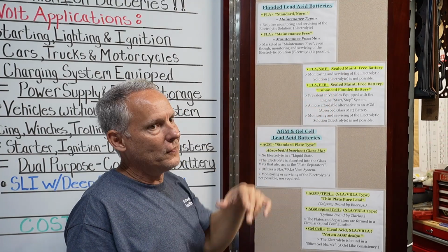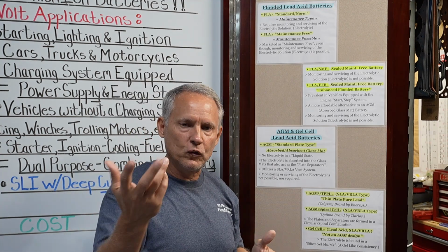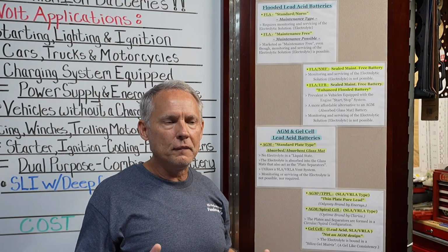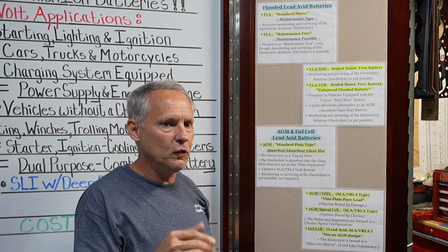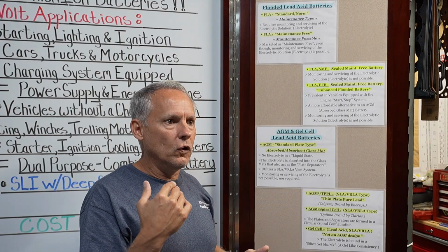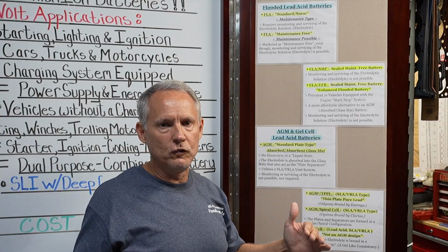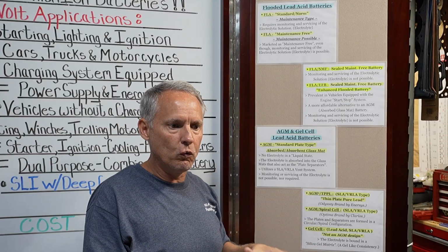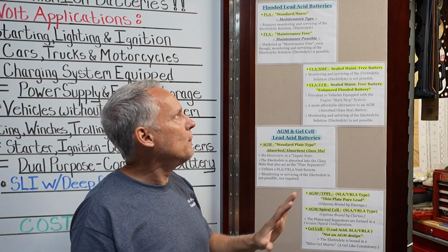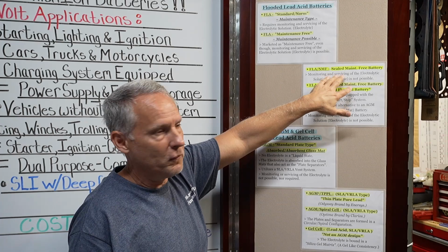Those three batteries are basically the same exact thing. Not to say that they're all, like if you go to a parts store and they say good, better, best. Is that always just marketing hype? Not necessarily. If you actually look at the ratings on the battery, you look at the warranty structure, they're not exactly the same thing. There is a difference. Internally, the batteries can be different. So there literally may be a structural difference inside the battery between good, better, and best. But they're the same type of battery, a flooded lead acid, standard, maintenance-free, or a sealed maintenance-free battery.